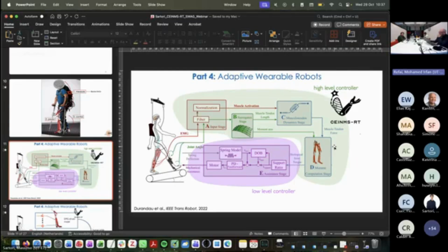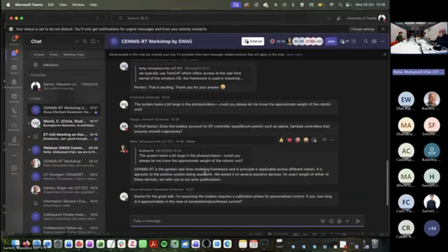So it will send basically similar values of torque in some time frames. But this doesn't matter because the low-level controller is running at way higher frequencies. The low-level controller runs at about 1 kilohertz, whereas the middle-level controller typically runs at 50 to 100 hertz. So it's normal to have this difference.